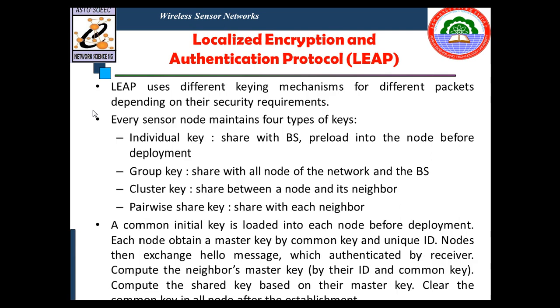In situations where no fixed infrastructure is available, some of the sensor nodes themselves act as beacons. Using GPS, the beacon nodes have their location information and send periodic beacons or signals to other nodes. In the case of communication using radio frequency signals, the received signal strength indicator, which we can call RSSI, can be used to estimate the distance. The time difference between beacon arrivals from different nodes can be used to estimate the location. There are several multilateration techniques, which we will discuss later after this.